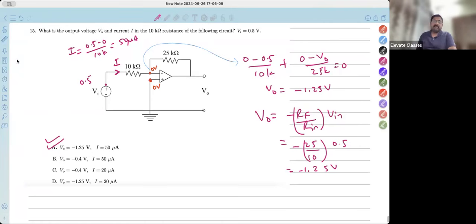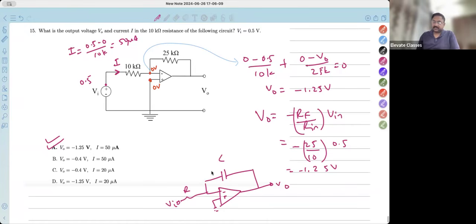Okay. When is an op-amp an integrator? When capacitor is in feedback. Capacitor agar feedback में हो, तो op-amp behaves as an integrator. और input में क्या होगा? Resistor. And if this is reversed, if input element is capacitor, then it is a differentiator. Integrator, differentiator, don't forget, that is very, very important. Integrator and differentiator are good, important questions that you'll have many times in your exams.